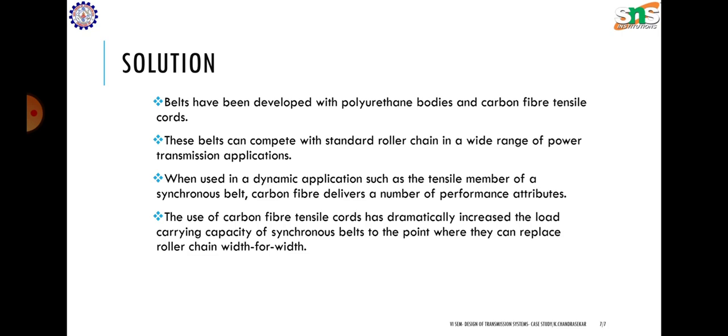So a special belt has been developed with polyurethane bodies and carbon fiber tensile cords. These polyurethane bodies can withstand temperatures above 80 degrees Celsius, and also the carbon fiber tensile cords.